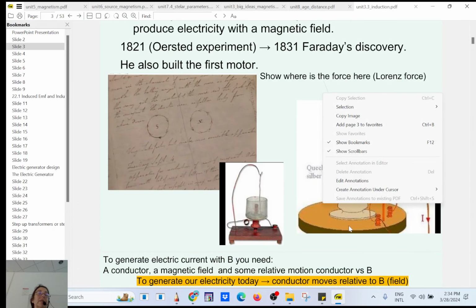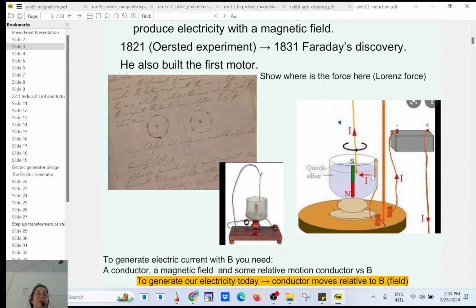Okay, so I want to make sure that now it's clear. Again, magnetic field is parallel to the magnet. That will be the current. So the current goes this way, magnetic field is up because it goes from north to south. So the force is into the screen. So it's going to apply a torque and make it twist.